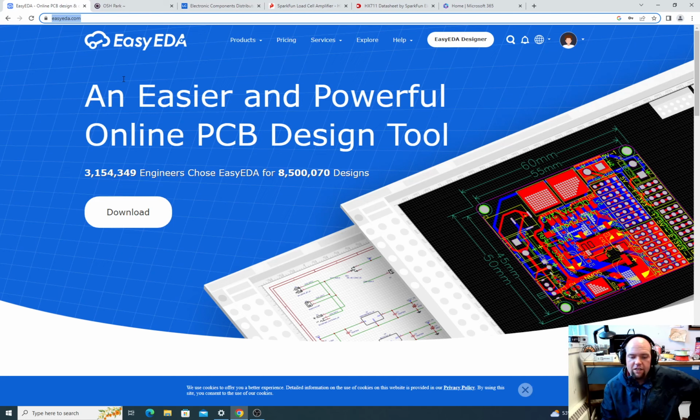I'm going to try to take you through all the steps that you would need to do anything with a PCB design. But there are lots of different EDA softwares available. EDA stands for Electronic Design Automation. It's basically a tool that allows you to symbolically represent electronic components in a schematic, and then it translates those schematics to the physical layout. It does that by connecting the physical pins and footprints for a component, for a chip, to the symbolic pins and symbolic connections.